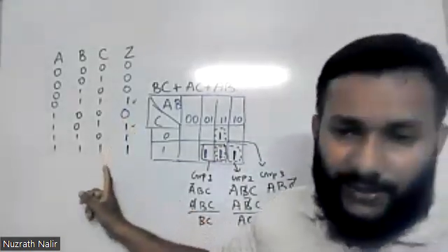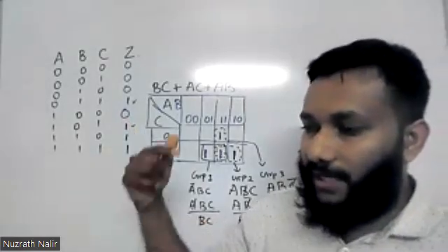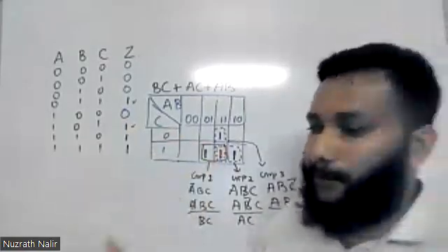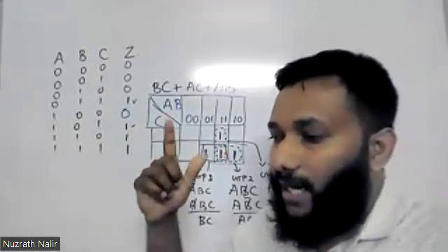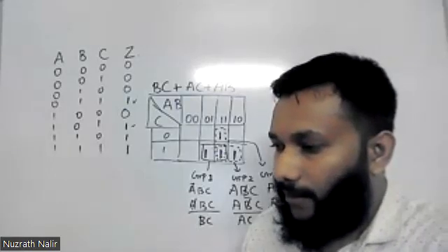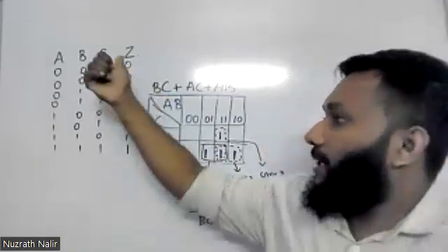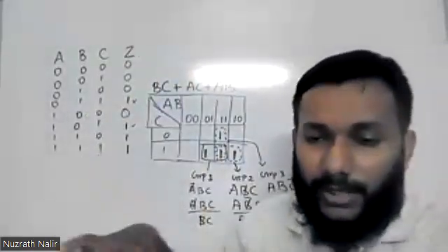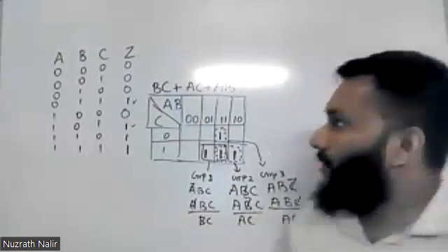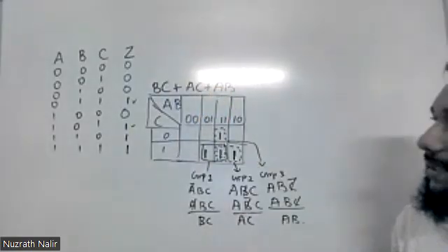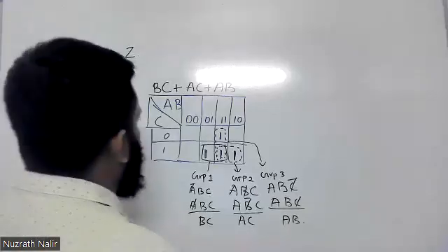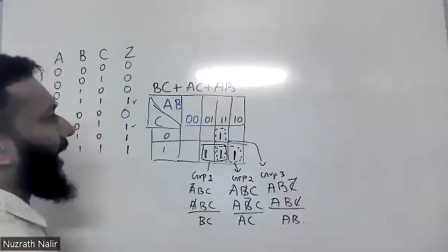The majority function takes n binary inputs and outputs 1 if a majority, at least half of the inputs, are 1, otherwise it outputs 0. Without the expression, you can't draw the logic circuit diagram. Therefore, we use BC, AC, AB as the answer. This is the logic expression.